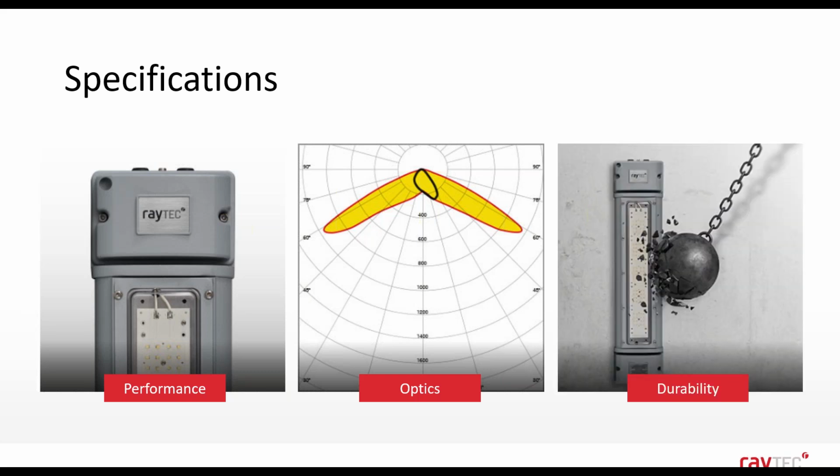And lastly, just to mention as well, durability. So look at things such as the materials which the luminaire is constructed from, look at its IK and IP ratings, temperature ranges too. Ensure that the luminaire meets the demands of that environment where it's going to be installed. And if you're unsure, and if you can't find that information, ask the manufacturer. Can they provide you with supporting evidence to show what testing the luminaire has been through, and to provide you with some evidence that will be suitable for where you intend to install it.